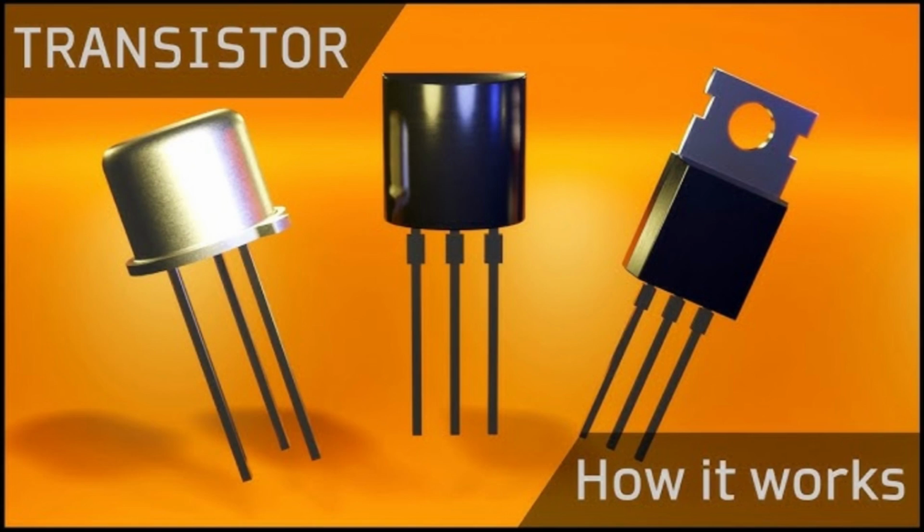4. Reverse active mode, reverse amplification. BE junction reverse biased, BC junction forward biased. Current flows in the reverse direction, collector to emitter. Purpose: rarely used in practical circuits. Effect: the transistor operates with much lower gain. Beta is very small.